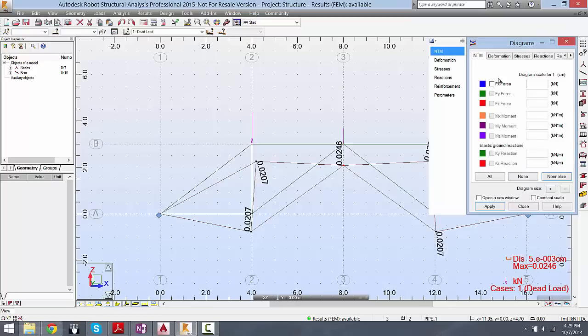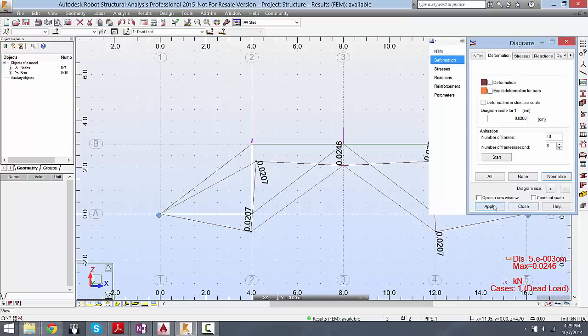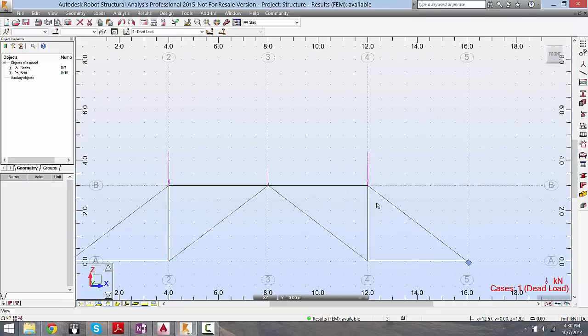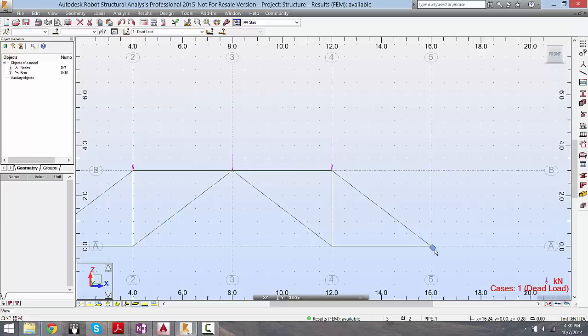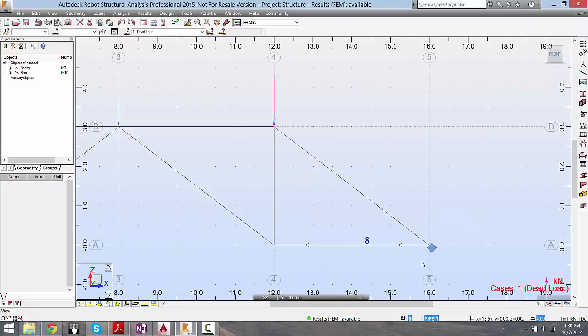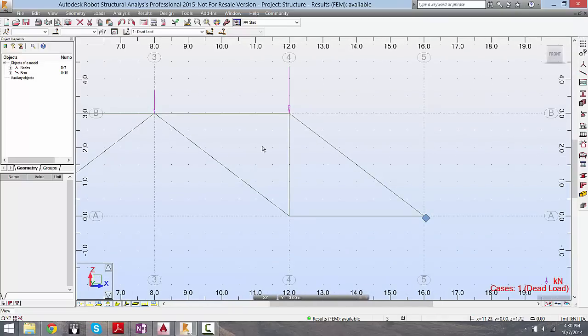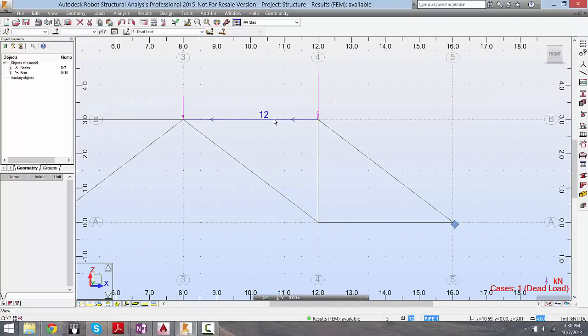But as I was saying, I'm gonna go ahead now and change. I'm gonna put on some initial load cases, such as a temperature increase or an initial displacement at a support. So these are added like forces. I'm gonna go ahead and put a, let me see, 5-degree increase on member 12 right here in temperature.